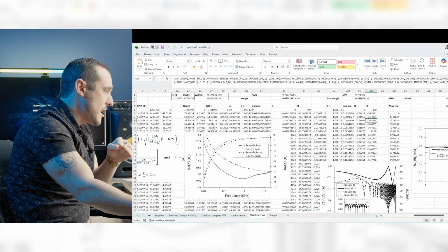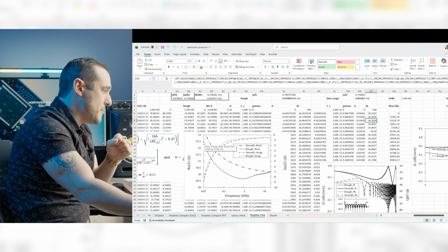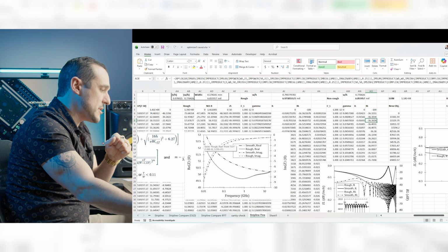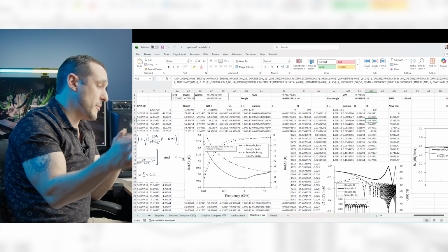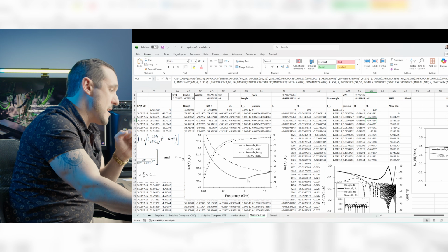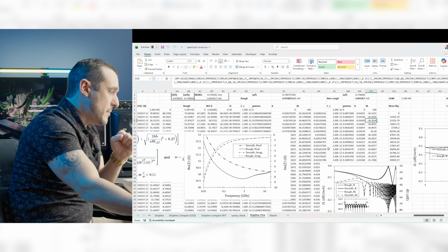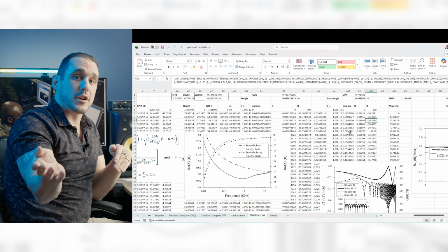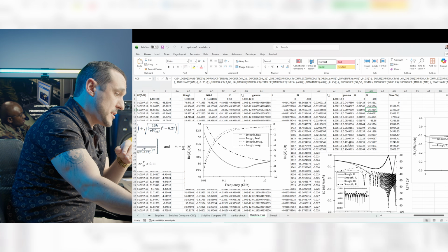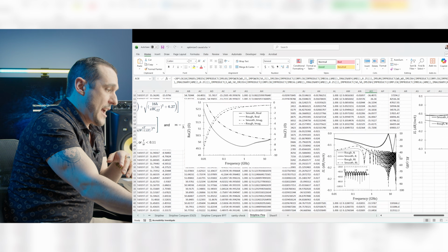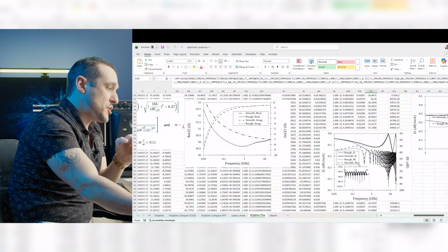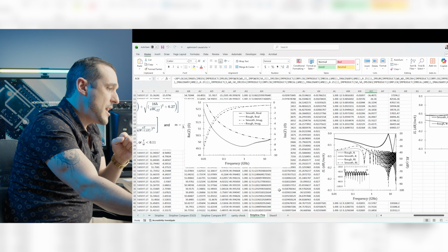And you can see here, it looks like it has very high impedance starting out at low frequencies, which is exactly what you would expect from the model that we showed earlier. And then it reaches some minimum and eventually starts to slope upward again due to the skin effect resistance. You can also see here that it calculates a return loss and an insertion loss. So that's what's shown here in this view.